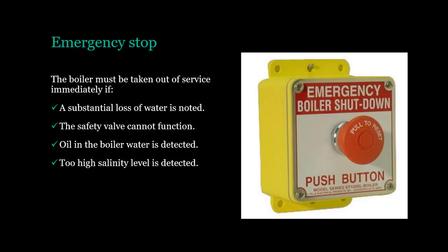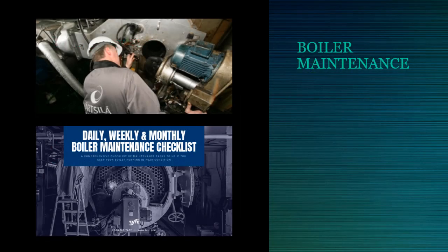Emergency stop. The boiler must be taken out of service immediately if a substantial loss of water is noted, the safety valve cannot function, oil in the boiler water is detected, or too high salinity level is detected. Boiler maintenance.